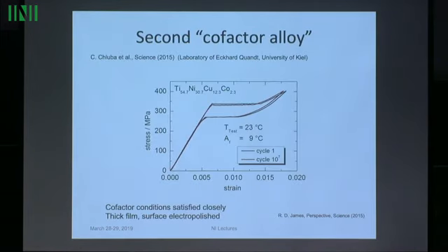But it's much more spectacular than that, because in this graph, again, it's 400 megapascal stress each cycle, and it's full stress-induced transformation. The black curve represents cycle 1, and the red curve is cycle 10 million. So that's what we would need for energy conversion devices. So this geometry, just the way the phases fit together, has a profound effect on not only the microstructure, but the properties and the reversibility of the material.